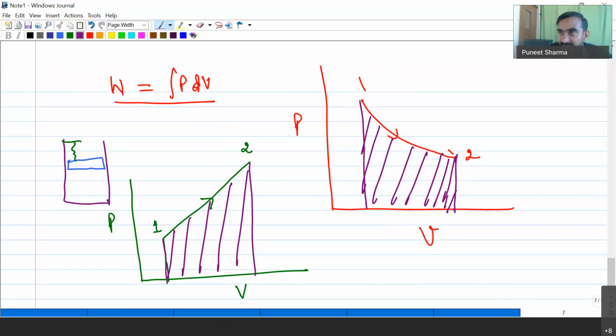Apart from that, in the case of gases we have one more assumption, the ideal gas. When we consider that our gaseous fluid follows ideal gas behavior, the properties depend solely on temperature. That's why for an ideal gas we have only a single temperature-based property table.